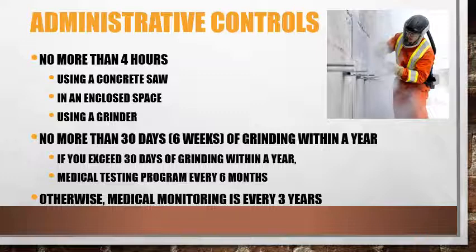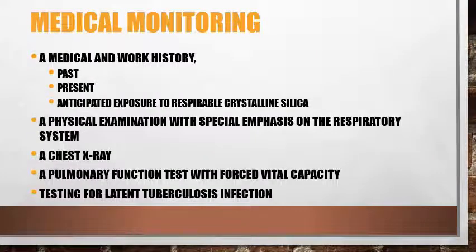If you're using a grinder for mortar removal more than 30 days, which is 6 weeks of 5 weekdays, within a year, then you need to be a part of a medical testing program every 6 months. If you're not grinding more than 30 days a year, then you can be tested once every 3 years. The employer is also responsible for medical monitoring.